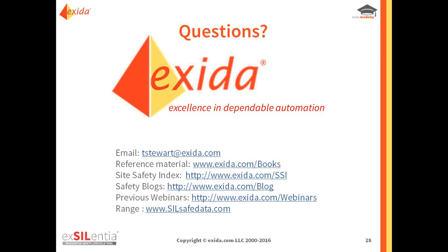It seems you place more faith in predictive lambdas using the FMEDA than in field data. Certainly you make some great examples of this. Okay, well, yes and no. What you need to know is, like we've done in previous webinars where we explained, it's important that any predictive lambda be based on field return data that has already been validated. You can think of it as a closed loop feedback mechanism: if you have validated field failure data, it must be used in an FMEDA to get realistic results.